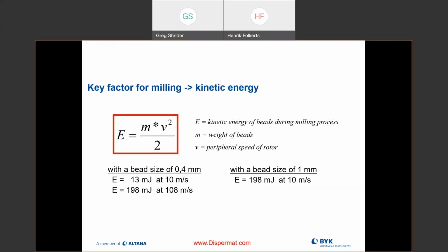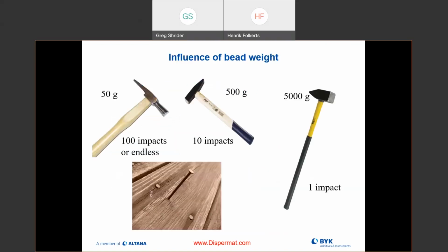But more importantly, you want to have beads with a high specific gravity, because that will give us also more kinetic energy. And as you can see already, kinetic energy is really critical in our deagglomeration phase, because if I have light beads, they're going to either increase my velocity by a lot to increase that hammering of my beads, or I just use heavier beads. Therefore, each flow of my beads, as they drift towards each other, just gives a much higher shear rate.